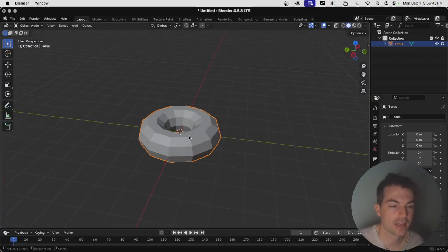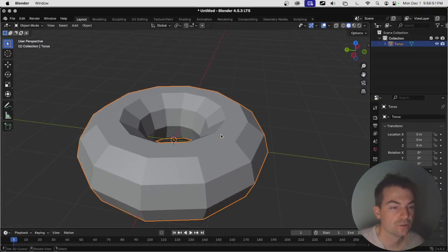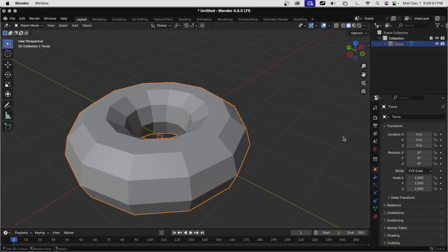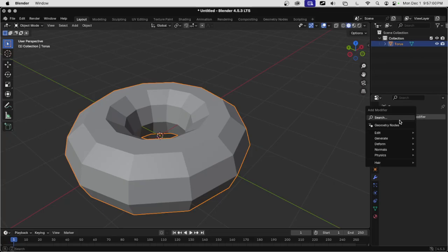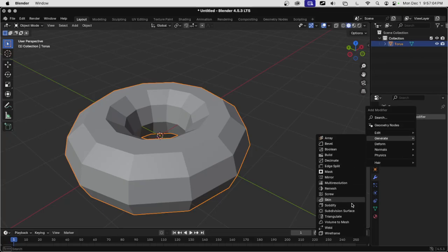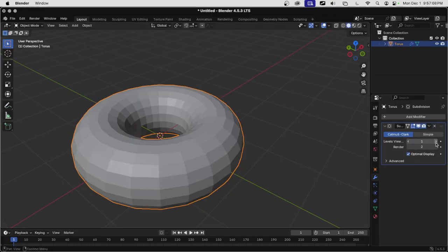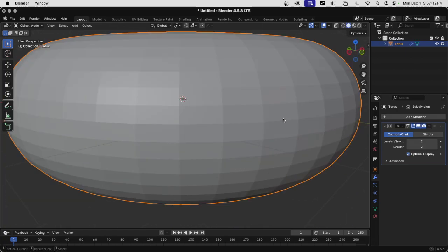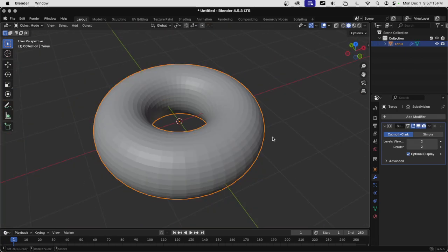Another thing that we can do is add to the resolution. So you can see all the points here, and so we can see these kind of flat surfaces. But if I hide myself for a moment, if I go into the modifier and I just add a little modifier here, I can add more data. And as I add more points, notice that this donut gets more and more smooth. And so let's do one more. We'll make this really exaggerated, and then I'm going to apply this.